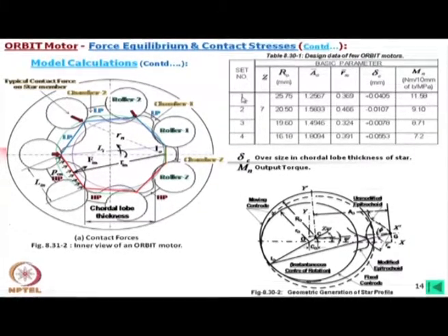If you look, for example, at set 1, that is one machine, you can see this is the dimension, plus some value. What does it mean? This is the tooth thickness. If you use a simple caliper, you will find that there will be some portion of the curvature whose tangents are parallel. So, we measure this distance.